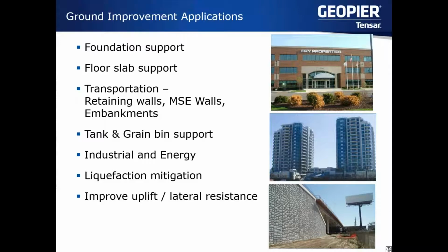And fast forwarding 30 years to today, the present day, where do we see ground improvement technologies being applied? And really the answer is everywhere. The intermediate foundation market, as many of us probably think of it, involves the support of buildings in terms of foundations and floor slabs for pretty much any type of building imaginable. And now normally there's an upper limit to the size of buildings which we're supporting. We're typically not supporting high-rises in downtown Chicago or St. Louis, for example. But we are seeing structures of increasingly larger size and loads, sometimes over 10 stories in some cases, being supported by ground improvement.